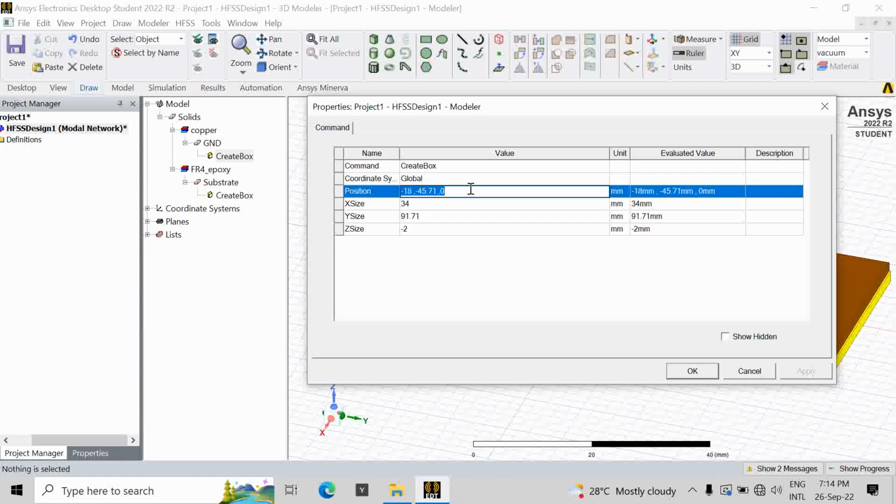Now we'll give a dimension same as the substrate, because we are using our conventional ground plane. We are not implementing any kind of enhancement technique, bandwidth enhancement or gain enhancement, so that's why our ground plane is conventional only. Since it has the same dimension, I'm not giving any new parameter. Whatever we have already defined, that is ls, the length of substrate, ws, the width of substrate, ts and all, that only I'm giving here for the ground as well.